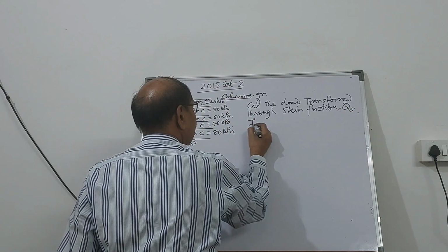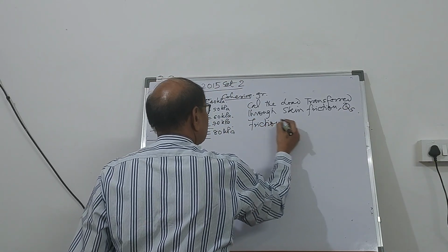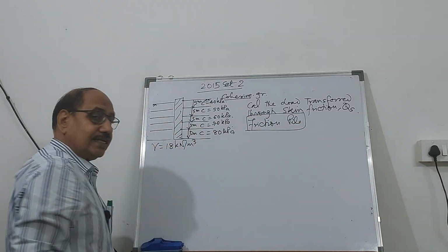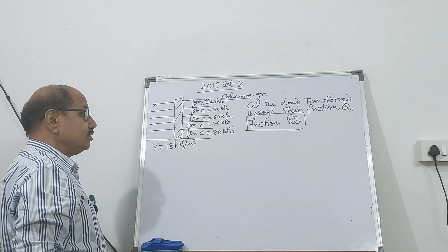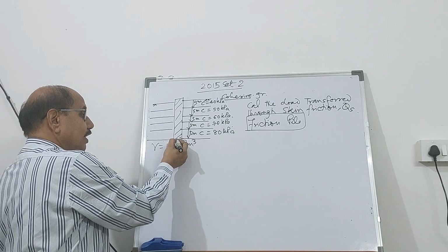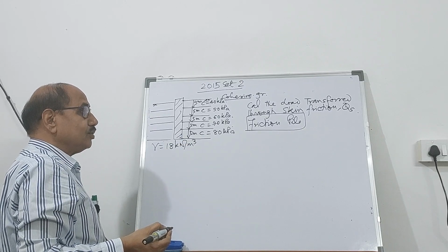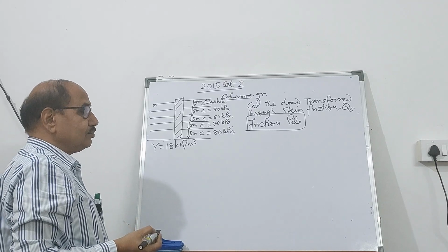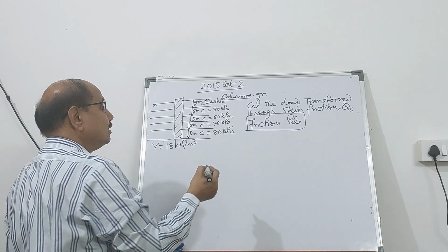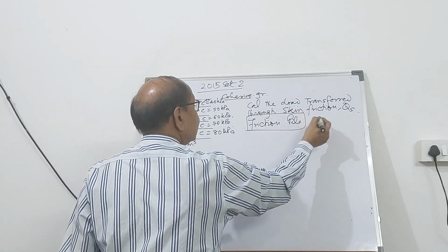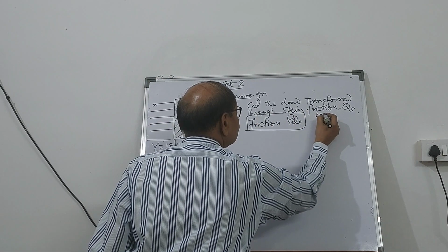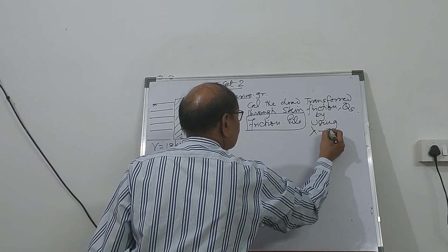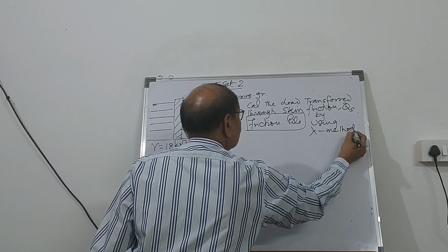This pile is a friction pile. As you know, in a friction pile, you need not calculate the end bearing resistance. The load transfer through end bearing is not taken into consideration, only through skin friction, because it is a friction pile. And you will have to calculate QS by using the lambda method.